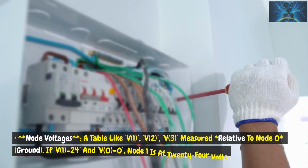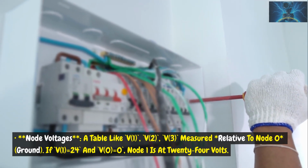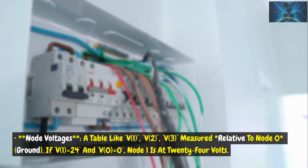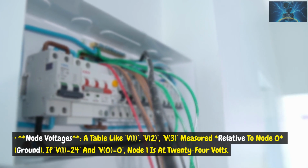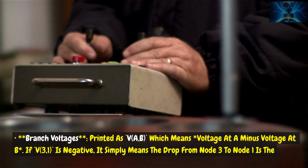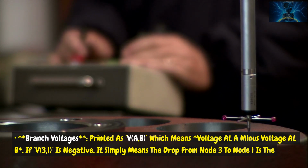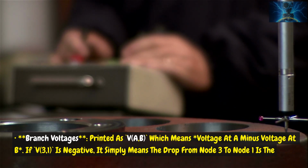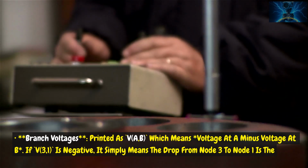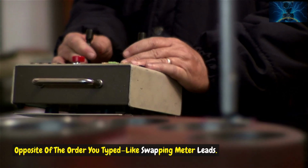How SPICE prints results. Node voltages: a table like V1, V2, V3, measured relative to node 0, ground. If V1 shows 24 and V0 is 0, node 1 is at 24 volts. Branch voltages are printed as V(A,B), which means voltage at A minus voltage at B. If V(3,1) is negative, it simply means the drop from node 3 to node 1 is the opposite of the order you typed, like swapping meter leads.